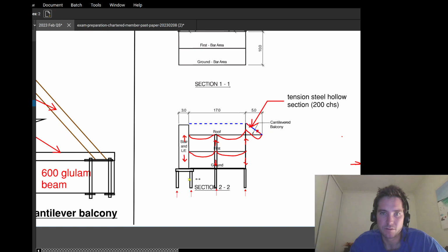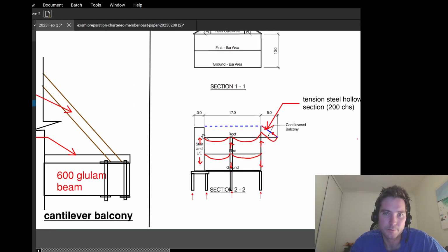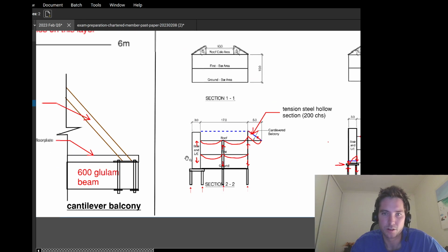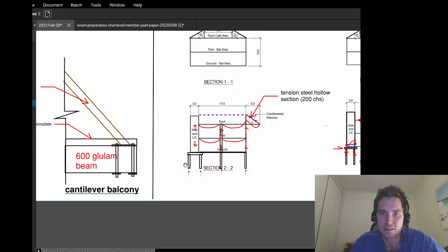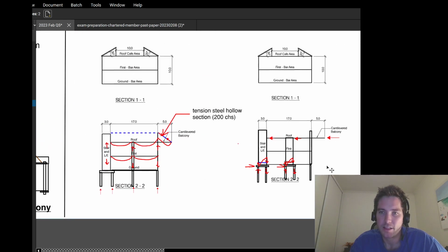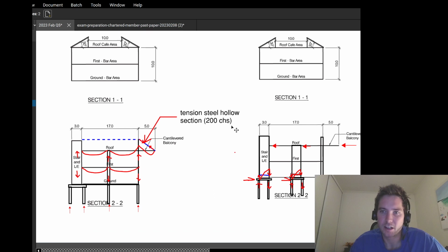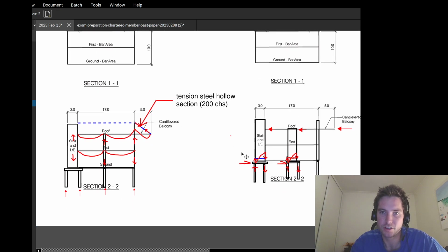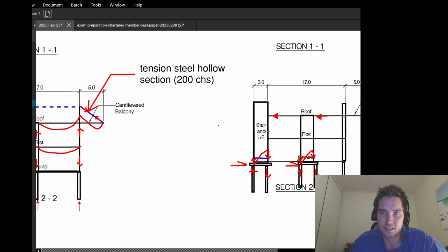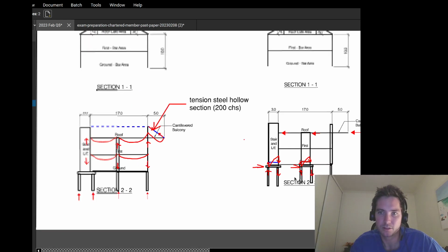My CLT core will take some of the lateral loads, and then it's coming down to that rock layer with my deep foundation. For my lateral loads, instead of using bracing, I've got the CLT wall acting as a shear wall. So here I'm just showing the load comes into my building and hits my two cores on an elevation, and the core does the bending, and then you get a push-pull on my piled foundation.